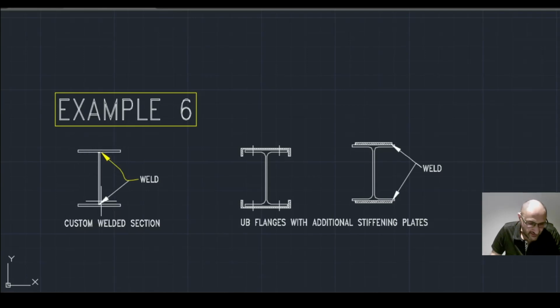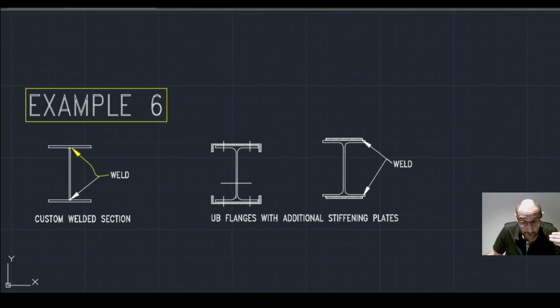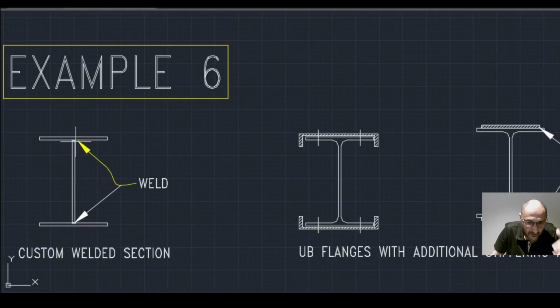Because of symmetry, you can take it from one side only. You don't need to check both ends. And again, once we know what the shear stress is, we can determine the strength and length of welds required to unify the whole section.